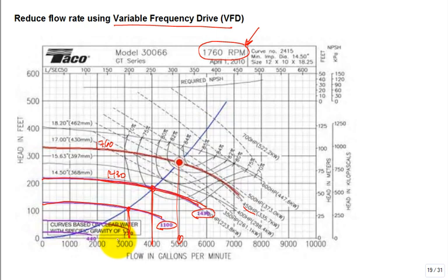And they can really have these VFDs go down to 20% of the speed of the motor. The motor can come down, it probably could come down to 15%. You have a little problem with possibly going to like 2% and 5%. What happens is you don't have the airflow that normally the fan is trying to move across the motor to cool it internally, and then you could overheat your motor. So you don't want to go too low, but these variable frequency drives have made a dramatic difference in the mechanical engineer's world.